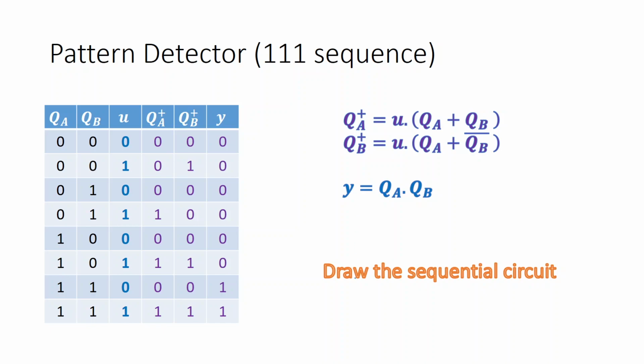Let us see. So when you are drawing the sequential circuit, mind one thing, you know how many flip-flops are there. You know that there are 2 flip-flops. As many flip-flops are there, you draw the flip-flops first. Draw these squares and draw them with some distance in between, because you don't know what logic gates combination circuit you have to place in between these flip-flops, so keep some distance between them.